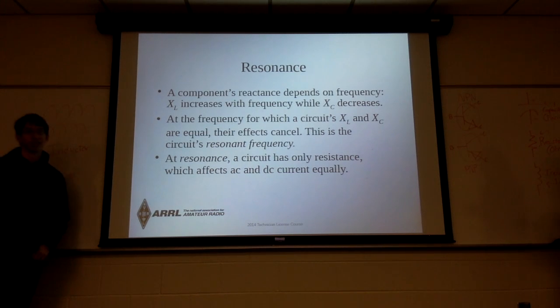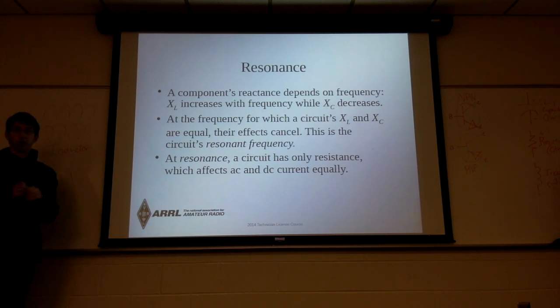All right, so resonance. When a circuit is resonating, you can essentially take out all the reactive components and are just left with the resistive components, because essentially, capacitors are the inverse of an inductor. At resonance, the energy in one will be transferred to the other at that resonant frequency, which means there's really no loss of energy between transferring between that capacitor and inductor, which means you can just kind of take it out of the equation altogether. The energy that's swapping between is not going to be involved anywhere else, and you're just left with any resistive component, is one way to think about it.